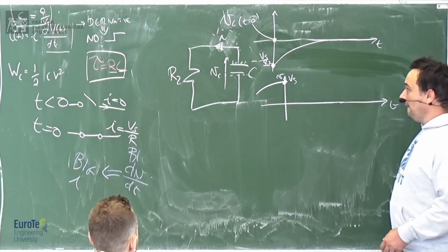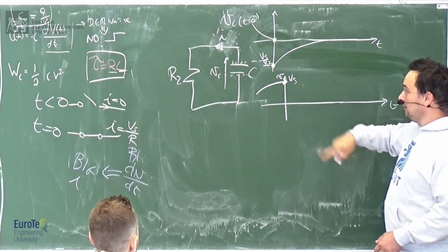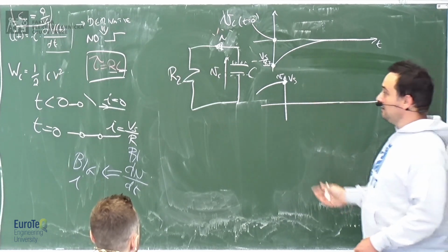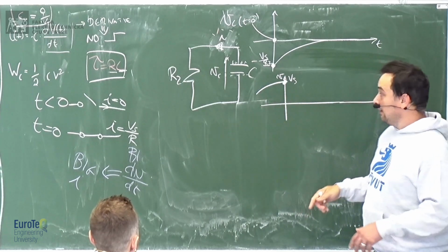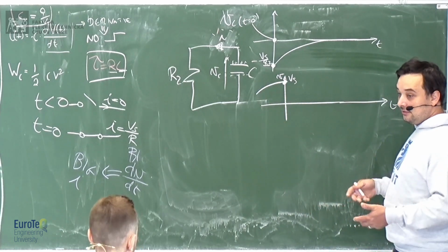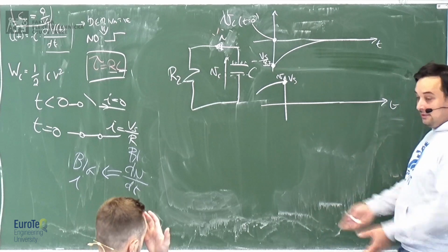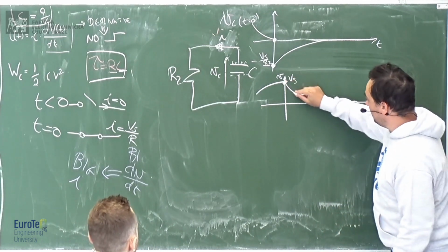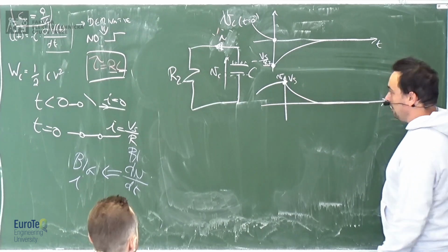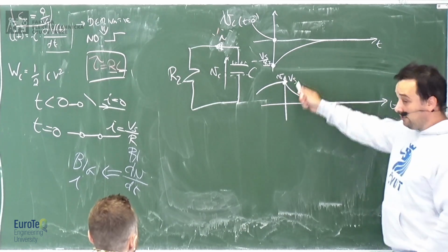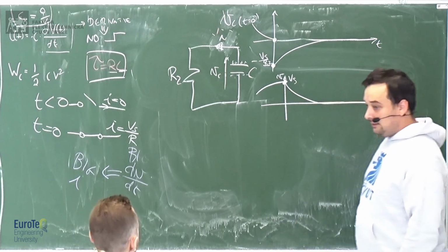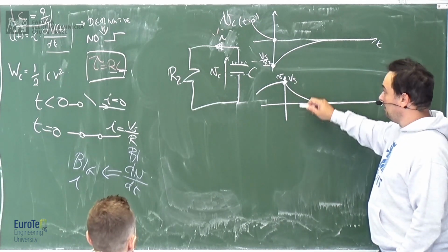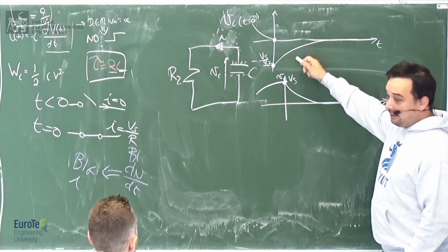And the voltage will have an exponential decrease. You remember that the voltage is the integral of the current. So if I take out charges, the voltage goes down. So it will go down to 0. Again, the voltage cannot change instantaneously, but the current can.